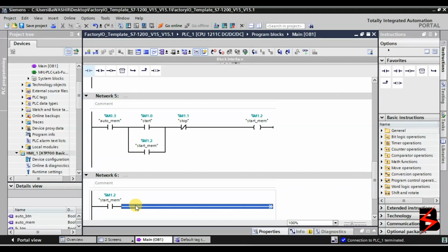We are going to have a sensor. Behind the sensor, you are going to have, now here a sensor is a physical component that you have to input into the PLC. Then we are also going to have another sensor. Then we are going to have, this is forward. Oh, it is a coil. Delete. Here I need a coil.